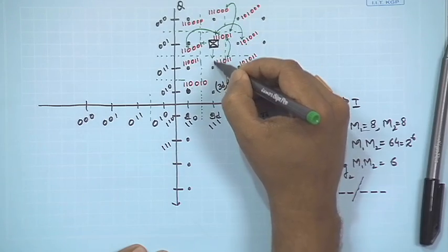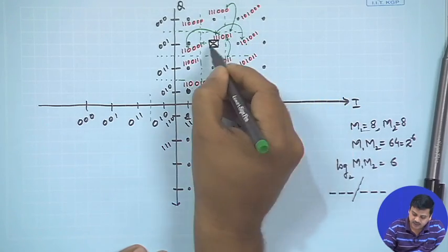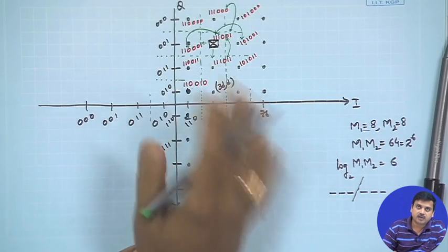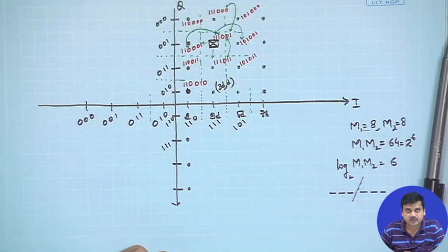So, there is a clear advantage in terms of simplicity, that if you are visualizing this as 2 PAMs, then you could use all your things that you have developed in case of PAM directly into this. The technique to be applied is you would take the component of the signal on the I channel, component on the Q channel, and you could proceed in the receiver.